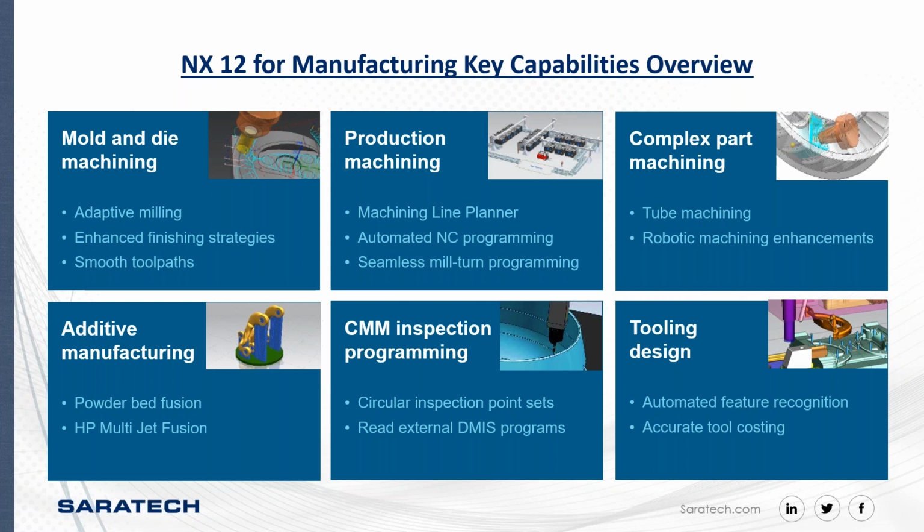They also did a lot of work in the CMM inspection programming with the circular inspection point sets that do not raise the probe up for more efficient tool paths. But they've also given you the ability to read in external DMIS programs, and that goes hand in hand with the simulation. We have the G-code emulator, which actually runs the G-code and not the NX code, the CLSF file, in the background. We all know that CLSF file, it's good inside of visualization, inside of NX's verification software, but there's a big difference between that verification software, where the tool rotates about the part, and a real life environment, where the part stays stationary or sits on the rotational axis and the tool physically moves.